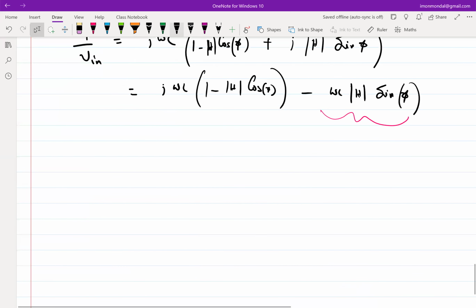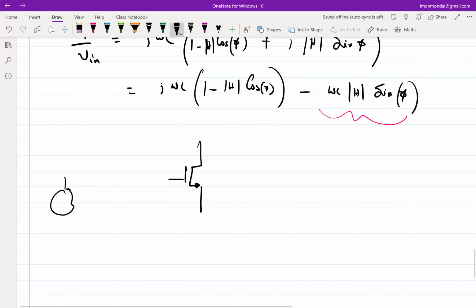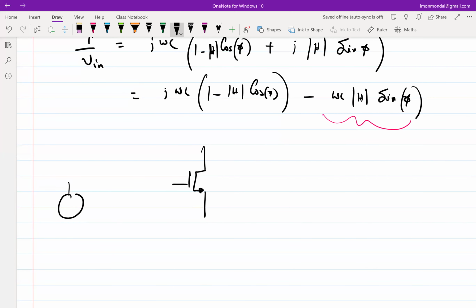We're doing this because ultimately we know that the best amplifier that I have is a common source amplifier, not a common gate, nothing else. We want a common source amplifier to get gain. Nothing else gives gain. So we want a common source, and we also want matching. If I connect it like this, it doesn't give matching. I have to put additional R and so on, which I don't want to do because of noise issues.